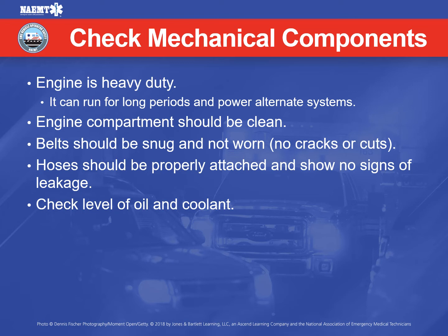Check the oil level. When checking the oil, the engine should be turned off for at least 5 minutes. If you need to add oil, use only the brand and type your service provides. Make sure you check the coolant level. When checking the coolant, the engine must have been off for at least 5 minutes to avoid a serious burn injury. Never open the radiator. Coolant systems usually have an overflow or fill reservoir to add coolant to if necessary.